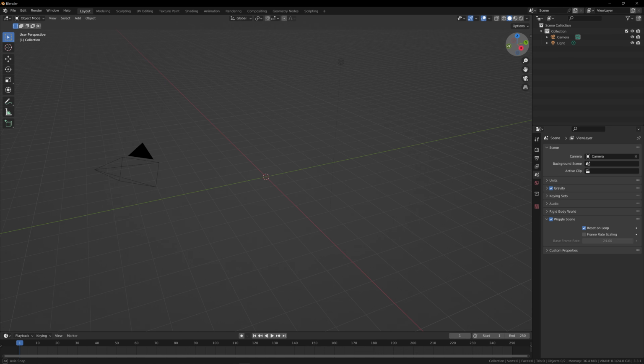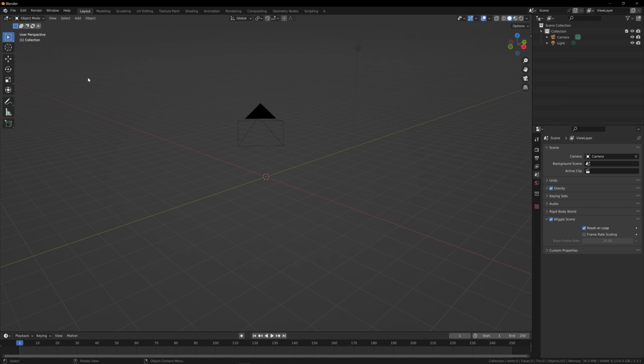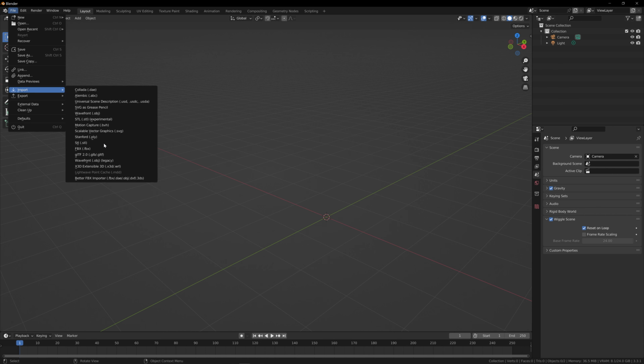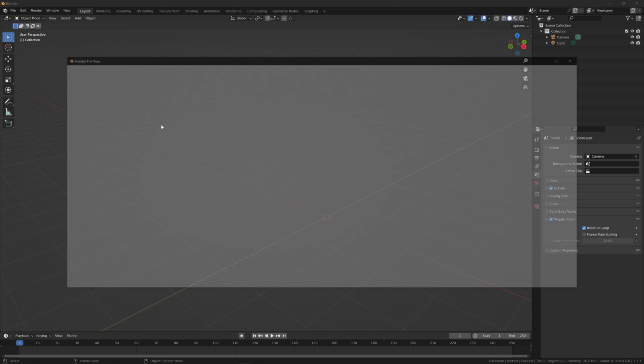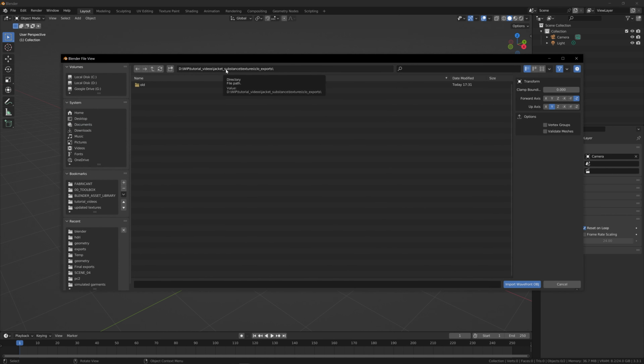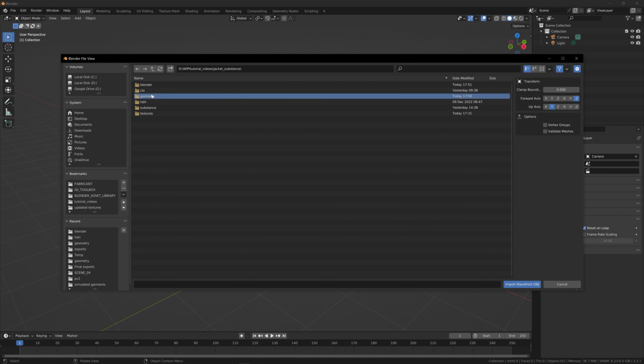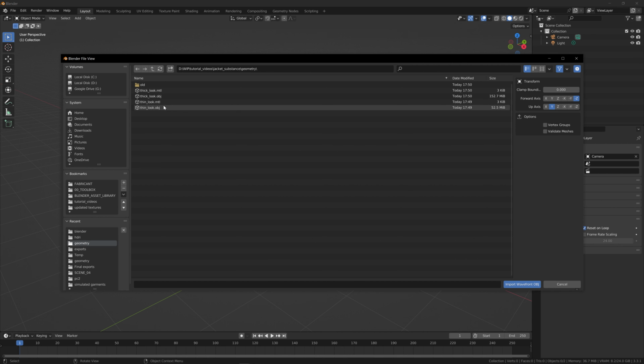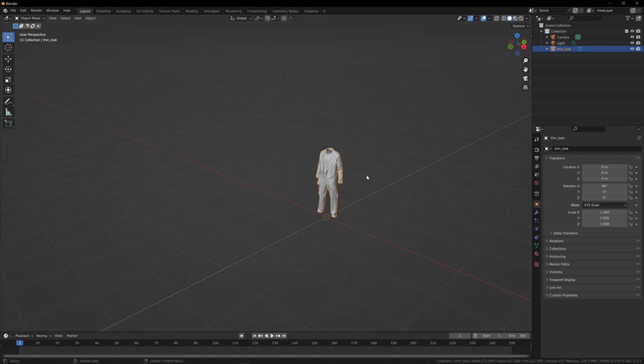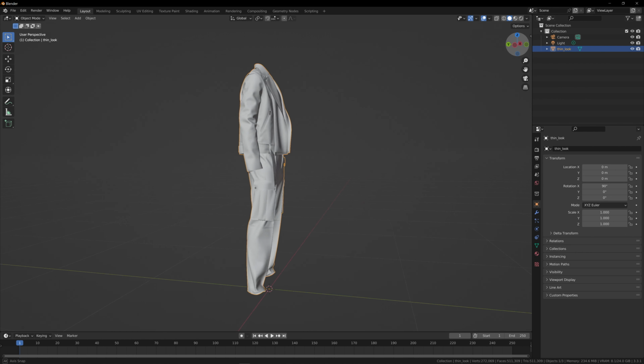I'm going to go quickly through Blender, so if you've not used it before, I do advise you watch the other video and get used to the workspace. But for now, we're not doing anything too complex. So if I go now to File, Import, and OBJ, and then I navigate to my exports folder from before. So I go to the geometry folder and I import the thin object. So if I import thin look and I click import, we now have our export inside Blender.